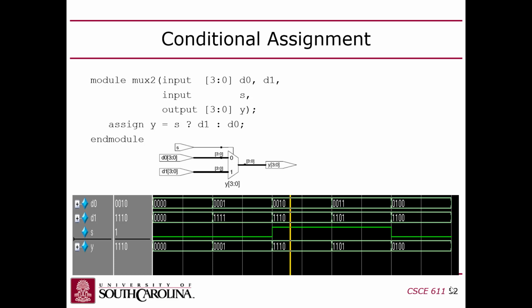Yes? Does Verilog have any kind of a macro language? Because I can see generating like a mux2, a mux3, a mux5. I think so, yeah. There's actually a .vh header; they have header files. And instead of pound, like in C and Java, it uses a backtick. So there's a backtick define in Verilog. I've never used it personally that I can remember, but yeah, you can do macros, sure.